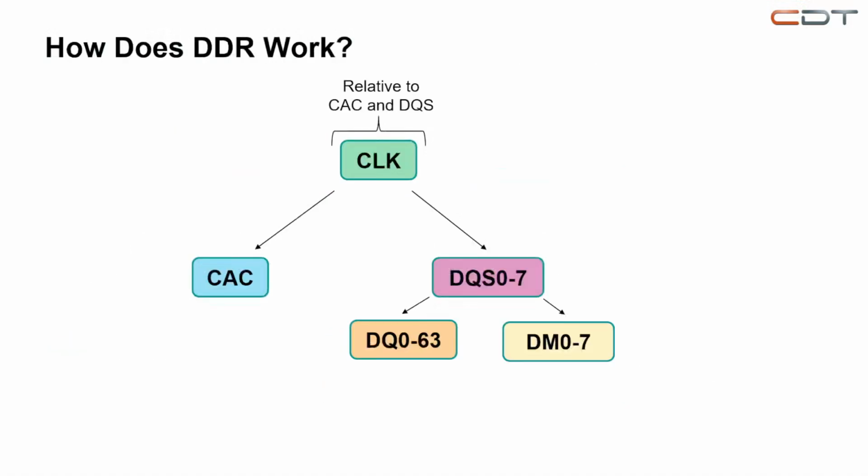Okay, so just to recap, I think most people on this call are probably very familiar with DDR. It's a double data rate interface, where we are reading on both rising and falling edges of the clock. Essentially, these are the most fundamental signals you would see. You've got the clock signal, which is the primary timing reference, and that's timing your address signals, which determine things like where you are reading data from, and it also times your data strobes. That's timing your actual data operations. Depending on which version of DDR you are looking at, this might look a little bit different. You might see write clocks or read data strobes, things like that.